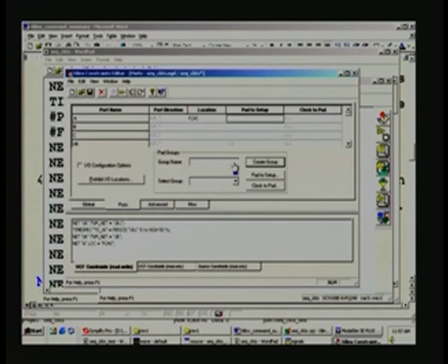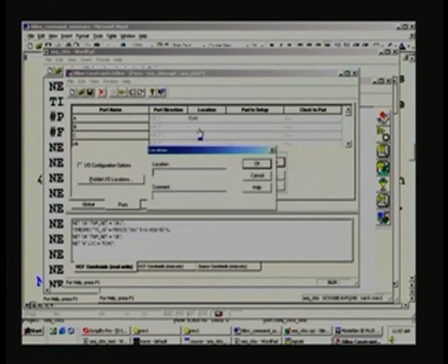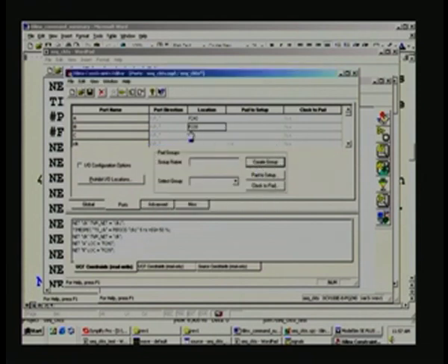In Ports here there is a pin column, say for example for this signal, let us say clock or B. I can key in straight away there, or I can double click here, another window opens, and you can key in there. I say 239 here and say OK, that gets reflected here. So, whatever is entered here also appears in the list.